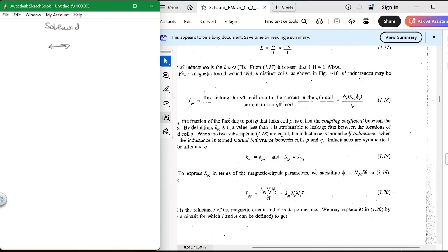It's got a spring on one side, and it's got a magnetic coil that you can energize, and it'll move one way, de-energize it, and it moves back the other way. So that's just an arm that goes back and forth. They don't go very far, maybe half an inch or a quarter of an inch, but that's what a solenoid does. It moves a little arm back and forth.